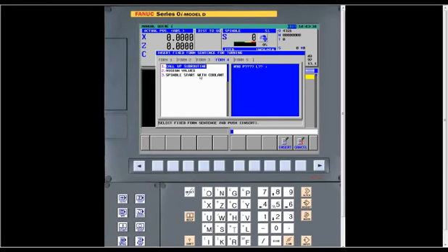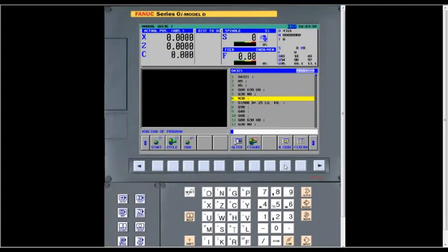Form 4, I've got calling up subroutine, or do a G10 assigned value type of thing, or just starting a spindle. Form 5 is just end the program. I've got a parts counter macro. I can just paste that into any program. And then when you actually want to put that within a program, you just press insert, and it actually adds it to a program.